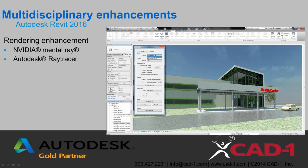So another great enhancement they have is the rendering engine. They've added the Autodesk Ray Tracer to your choices when you go to do a rendering. And so if we look up here, now there are two. We got the Ray Tracer and we have the NVIDIA. So we've got the Ray Tracer that's been available in your display options at the bottom of the screen. But this one is so when you actually go to do a rendering, then you can choose between the two.